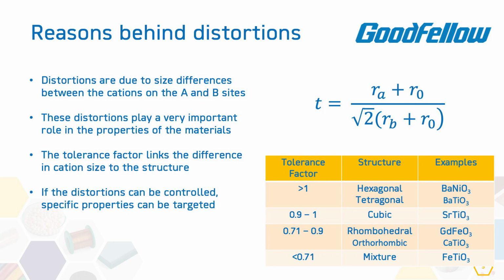But now imagine that the A cation gets smaller. This A cation, as I said, is coordinated to 12 oxygen atoms around it, 4 in the plane, 4 below and 4 above. And these oxygen atoms make up the BX6 octahedra. If this cation on the A site got smaller, because the oxygen-cation bond lengths stay pretty much similar, the oxygen ions that it's bonded to need to come in slightly. And when they do this, they pull on those octahedra and tilt them.